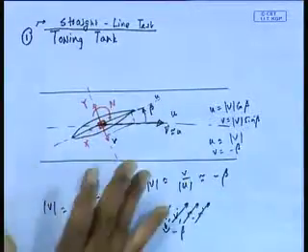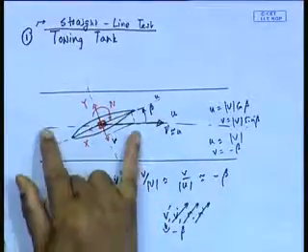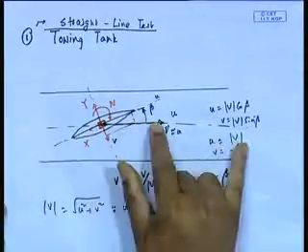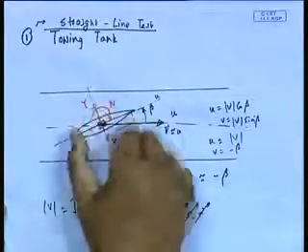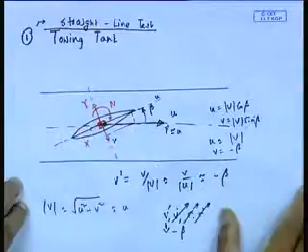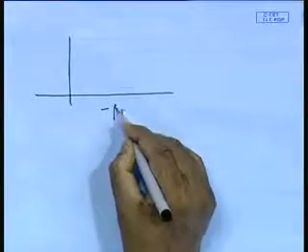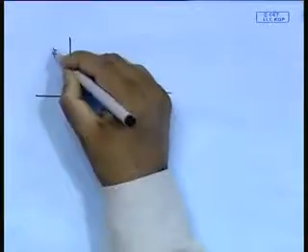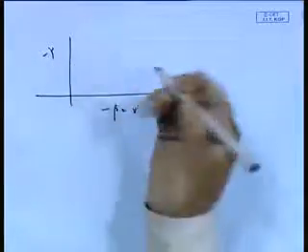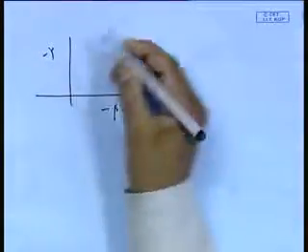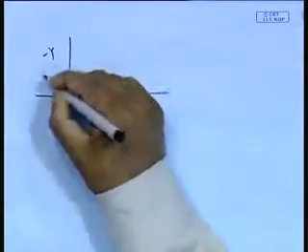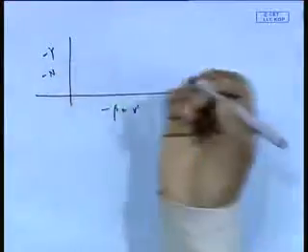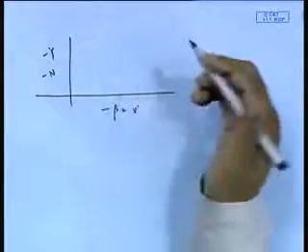So essentially I am doing this test where I could measure, for different beta, Y force and N moment. In other words, what I am achieving in this test, very interestingly, is that I have minus beta, which is equal to v dash, and Y, I put it as minus Y here, because typically otherwise the graph does not come this way, minus N maybe, or N maybe, it does not matter which way the N is.